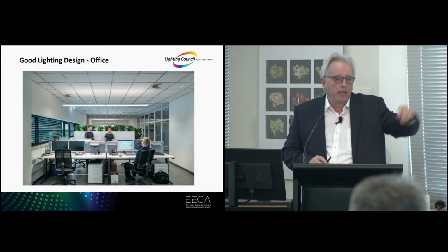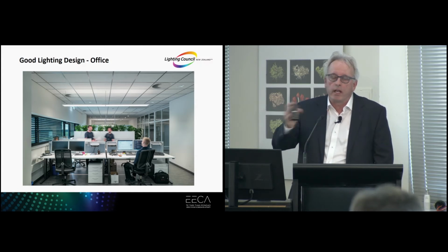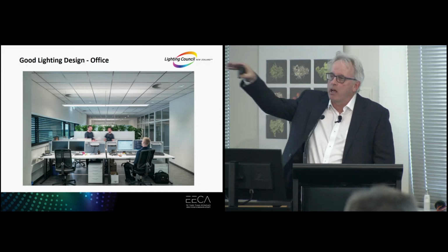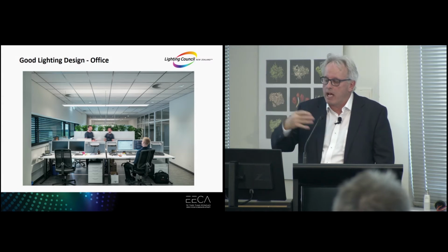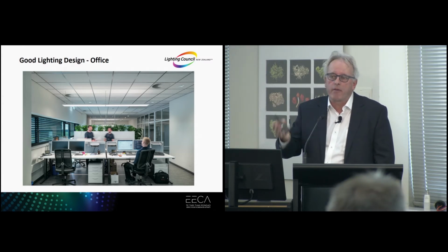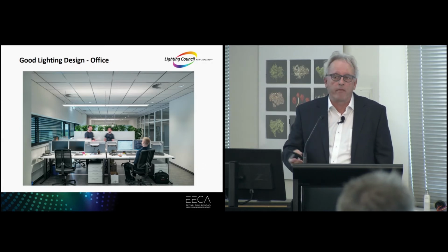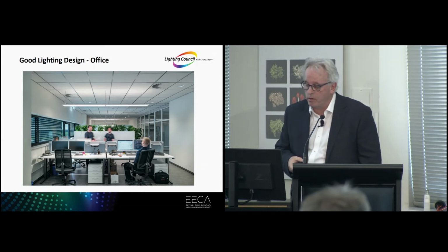Now we have little wee windows, maybe only along one side. We've also changed what we're doing in terms of we're no longer looking across the room, seeing the light fittings on our horizon. We're now looking at a screen, and the glare could be coming from the window. So glare from light fittings is important, but glare must be considered in lots of ways. It's glare from light fittings, it's also glare from natural light sources.